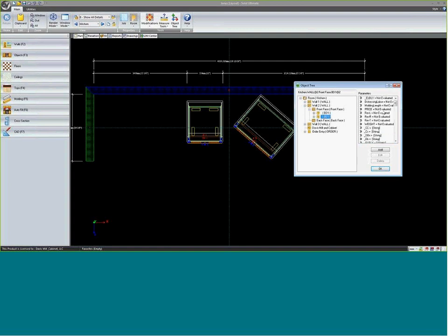Now if I go to this cabinet, let's look at its DX, DY, and DZ. DX is 534, so we know that's this cabinet in width. It's 880 high and 610 deep. But if I scroll to the bottom, in X I noticed it's 1400 millimeters away from the origin point of the wall. Y, remember we floated that 500 millimeters up off the floor, so that's our Y, 500 millimeters. Z is 100, that's how far in Z we are off of the wall.